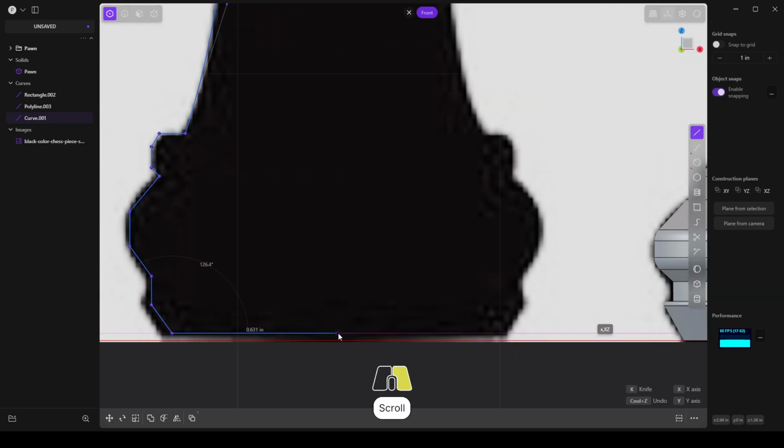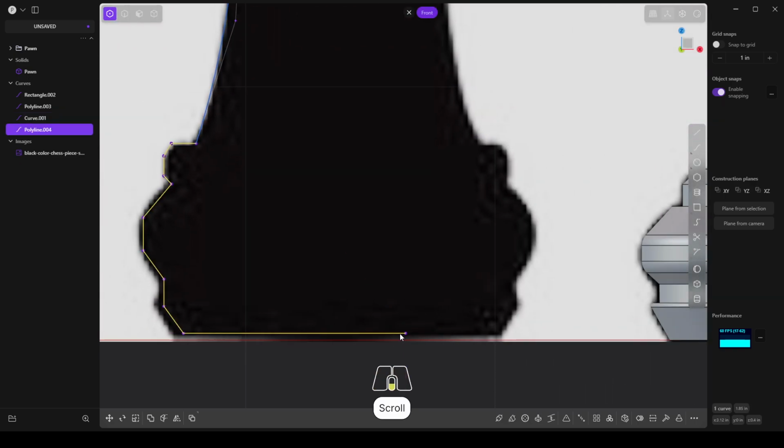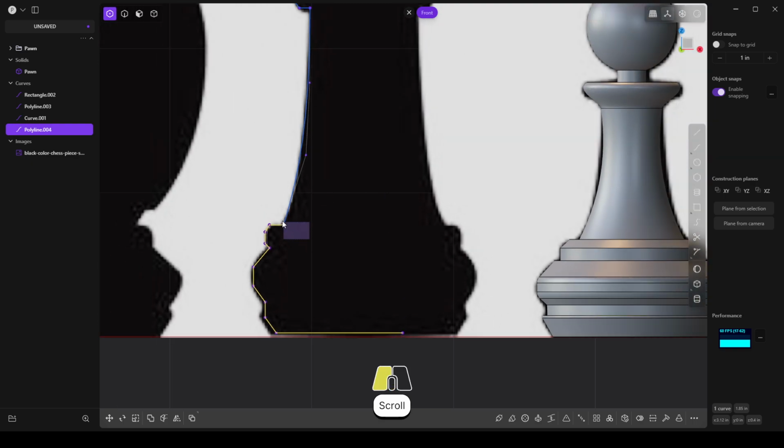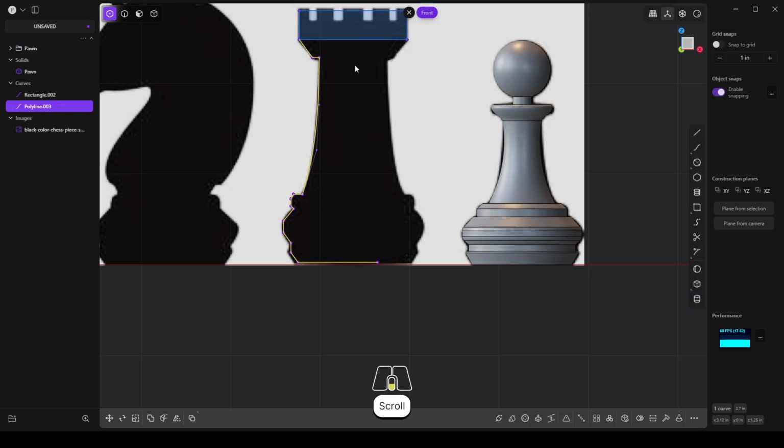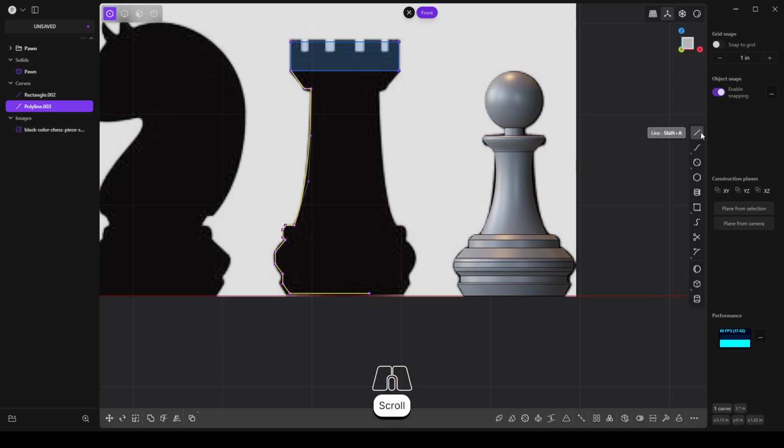And we can just grab this. I'll overextend it ever so slightly there. There we go. Just going to make sure these are joined. Select both points. Use J so you can see each of the new spline curves should now be joined. I'll use the line and it should snap to the middle. And there we go. Just to stop myself coming off a little bit there as well, let's lock that into the Y axis.